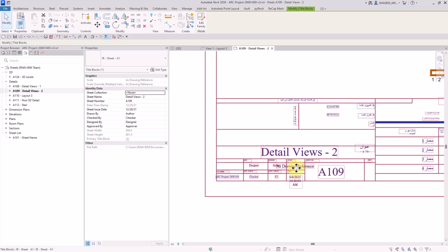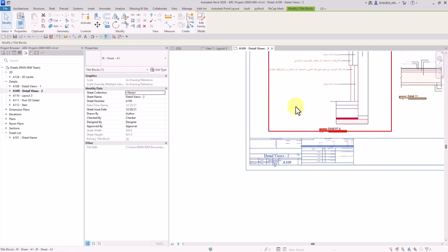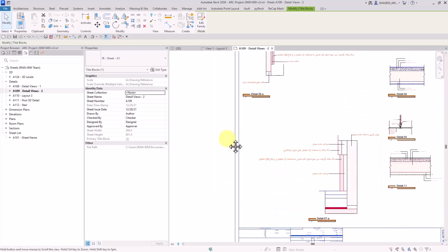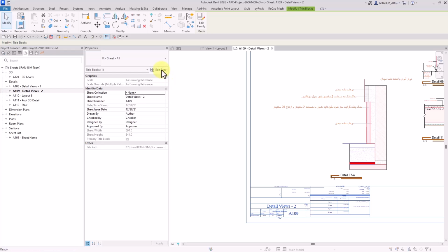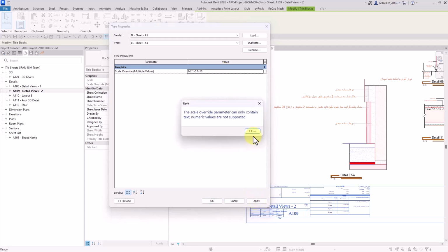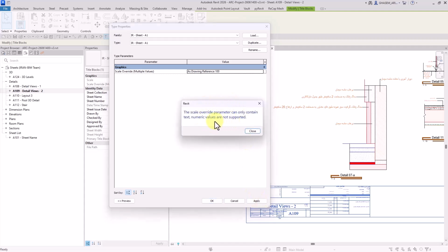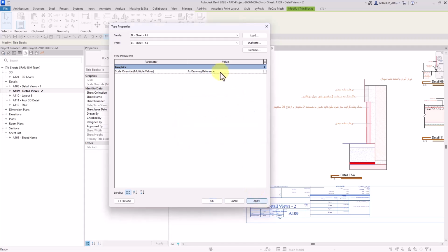And basically, guys, you can set whatever you want, or, it's better to say whatever you need to manage the sheets better. I mean, the best way possible. And remember, guys, you can't use numbers here. I mean, I can, for example, go with 100th. You know what? Let me change this to 1/2, 1/5, and 1/10. If I try applying this, I'll get an error. And we can't even combine the numbers, see? Again, we'll face another error. So, do not use any numbers in this field.